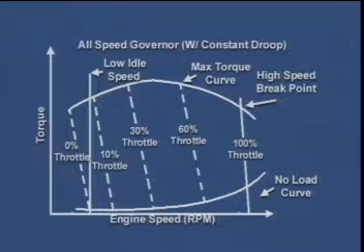Switch position 1 is enabled by default. This feature allows a change in the drop in engine speed when the engine is operating between the governor speed and the high idle speed.